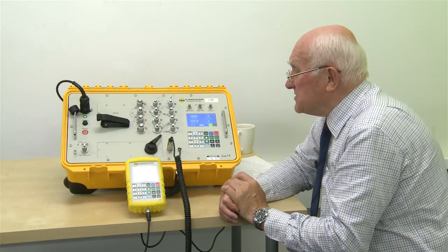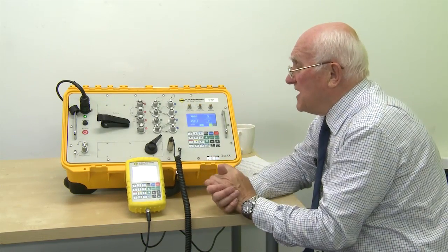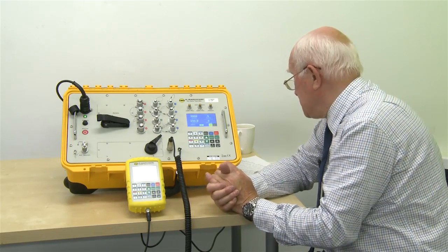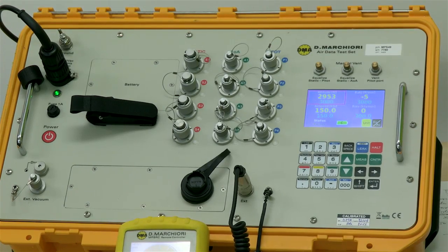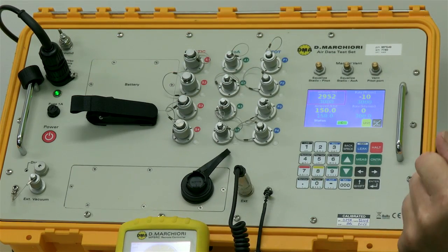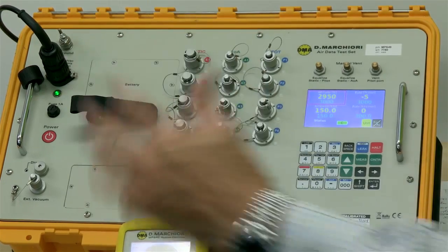The battery significance we've already talked about when we came earlier. The battery lives under this protective cover here. It can be removed, it can be replaced yourselves should it be necessary. Okay, we showed a few moments ago of how you can go into the leak test mode and then see what is happening to the aircraft in terms of what's on the static and the pitot. However, we've already pointed out many people prefer to buy multi-port so that they can cover the individual pneumatic ports you're using, for example, captain, first officer, standby, etc.